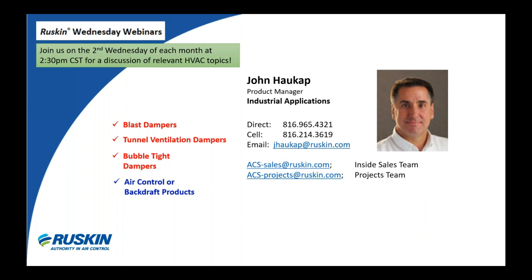Okay, another question is, how is the torque calculated for industrial damper models? Well, we have in-house generated software programming for each of our industrial damper models, and it's calculated based on pressure, velocity, and if the damper has blade and shaft seals. So it's not like the commercial grade dampers, where torque is assigned based on square footage and either 5 or 7 inch-pounds per square foot. Ours are calculated based on system conditions and the size of the product and the features of the product.